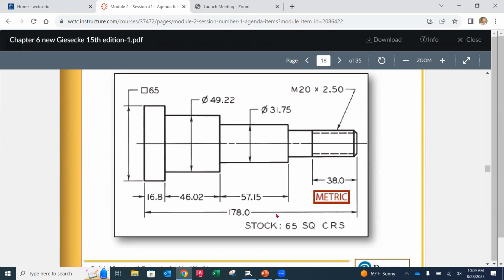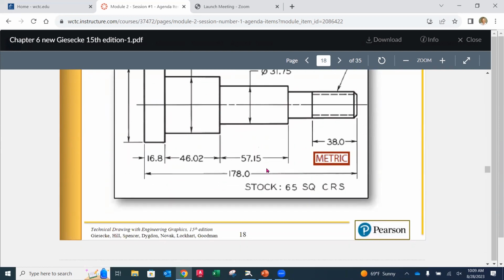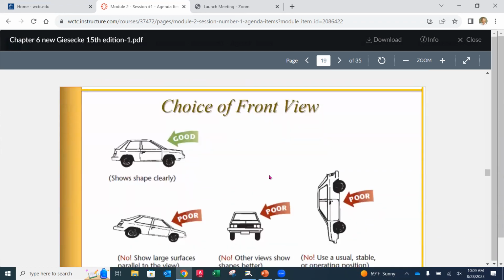So this is not a good idea, especially when you're sneaking in a square feature like this. So always err on the side of giving more information than needed to clarify it, because you don't want to assume, for obvious reasons, that somebody's going to catch that. And they're going to come back and say, oh, I didn't notice that. And all it would have taken was a simple extra view on your drawing to really clarify that. So not crazy about this. They're okay with it. I'm not.